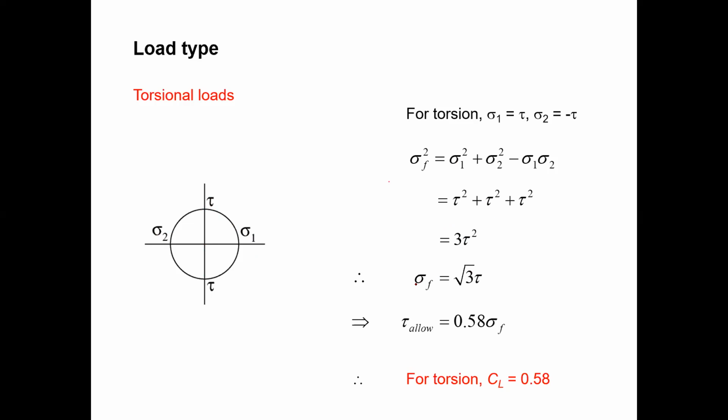So then equivalent stress is equal to root 3 times torsional shear stress. So this is the value. When you get the root 3 values, it is 1 upon root 3. So this is the relationship. Okay, so we need to multiply by 0.58. That is the load factor.